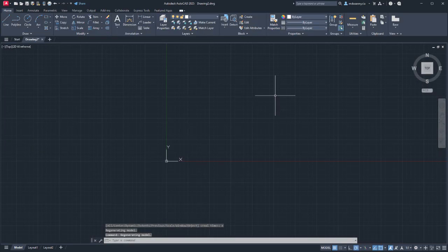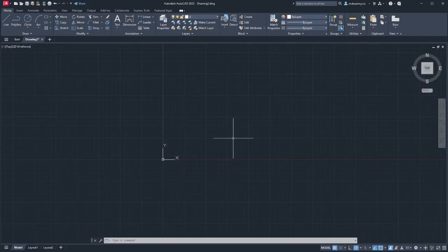It's really helpful, and occasionally another thing that'll happen is you'll load into the program and you will be stuck in a certain zoom level. You can't zoom very far out. Zoom extents will actually reset that boundary, and it's a really quick way to do it. There's another way to do it that I tried once, and it's a mess. Zoom extents will automatically reset that, so that's a helpful way of reconfiguring if you do get stuck.